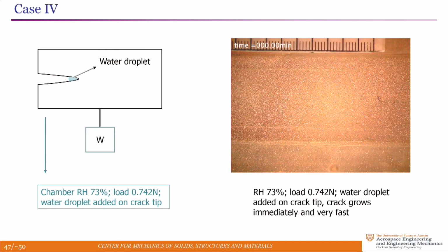Hello. In the last slide, when you put this water in the crack, are you planning to use some other liquid? Because if the liquid is more viscous, then there will be a lag between the crack tip and the water tip. It's a good idea, but we haven't done it. Here there is no lag between the crack tip and the fluid, but with high viscosity there might be. This is a 3-component system. It already has water and glycerol in there. Water is low viscosity, so it's easier to infiltrate, and it's going to be a greater lubricant to make the molecules move faster. If you put glycerol in there, it's going to take a longer time to infiltrate into the process zone. So I think the effect may be clouded more into the viscous process and not that easy to unravel. But it's a good thought. We'll think about doing some experiments in that direction.